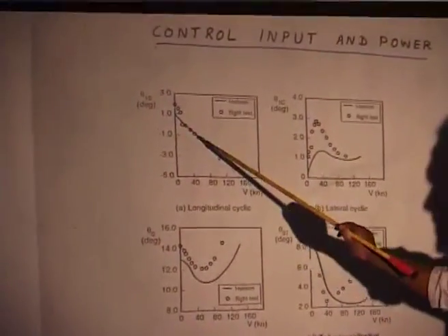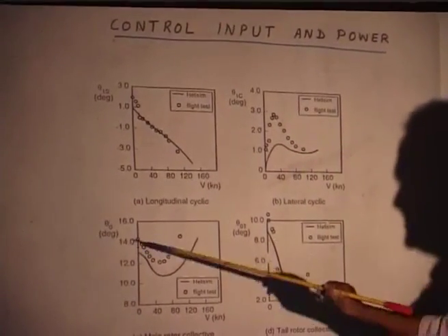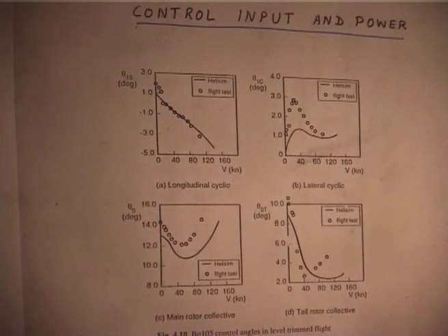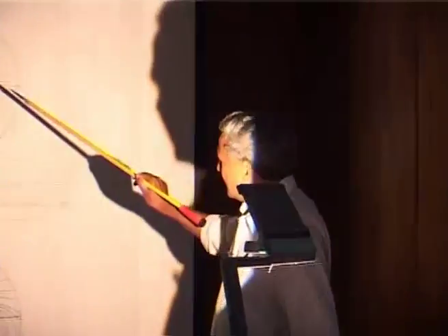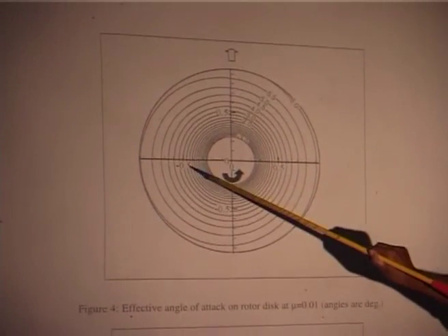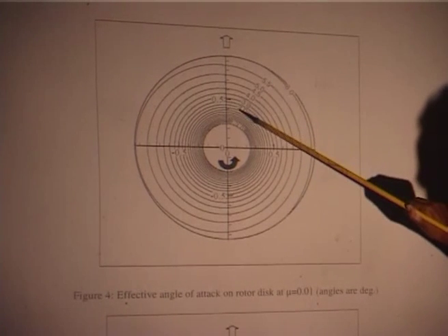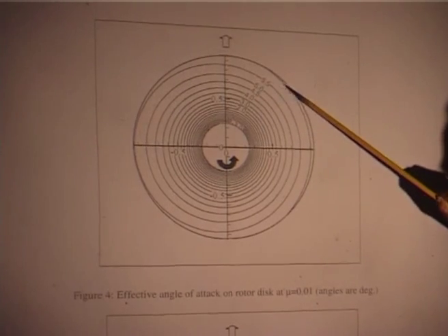Now, I will show you one diagram, it is interesting. This is what I took from the paper. These are all experimental data. This is the one I took, because for the other things everybody gets the trend, there is nothing special, only this is the key. I just want to show how the pitch angle varies. I have put the numbers here. This is 0.05, these are nothing but the midpoints of the rotor, and these small numbers 2, 3, 4, 4.5, 5.5, 6, these are